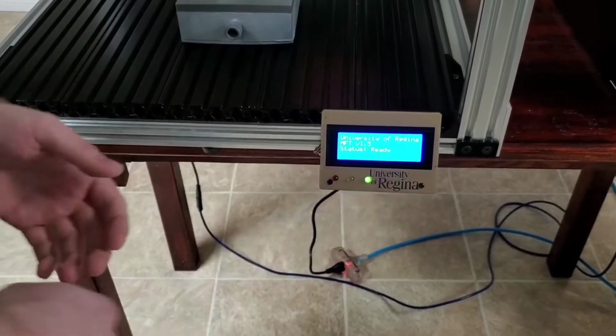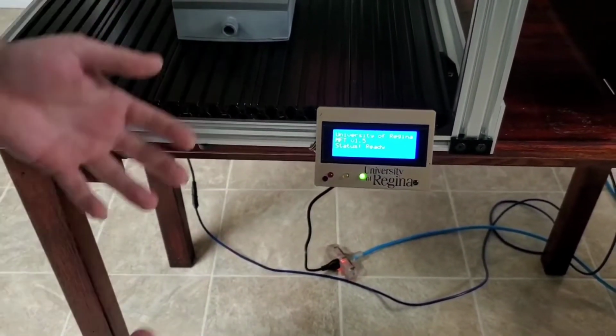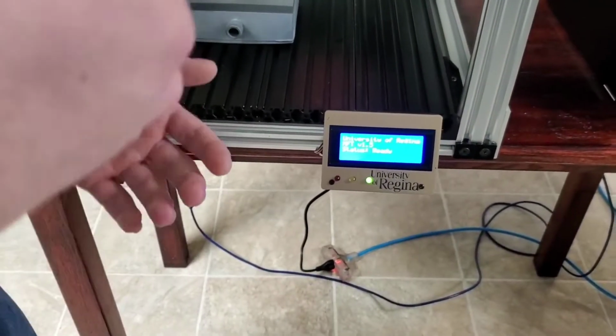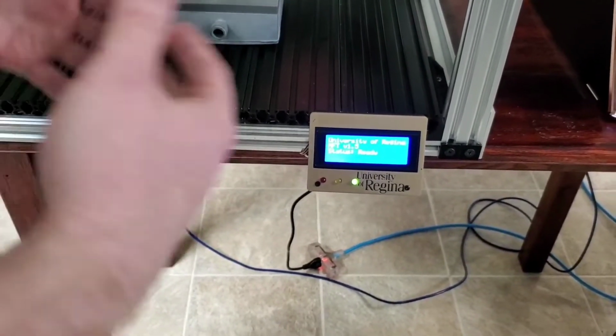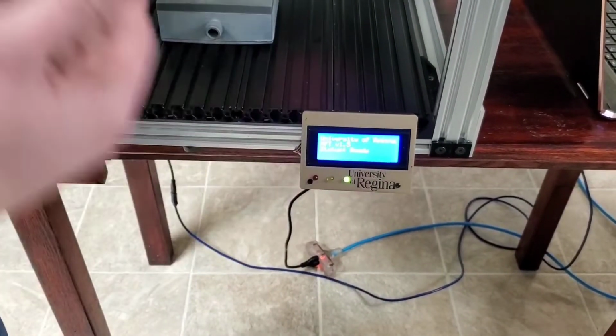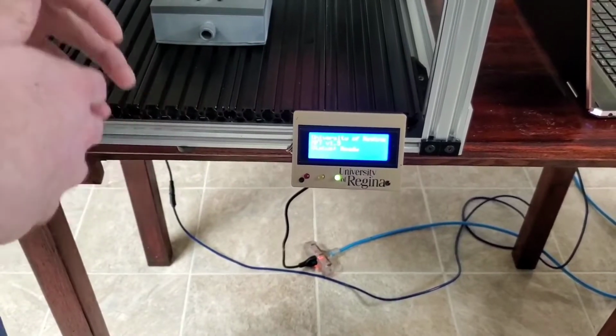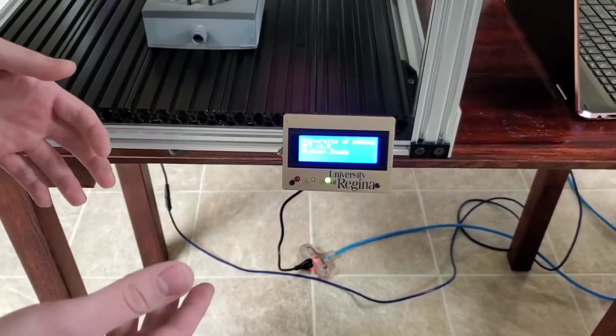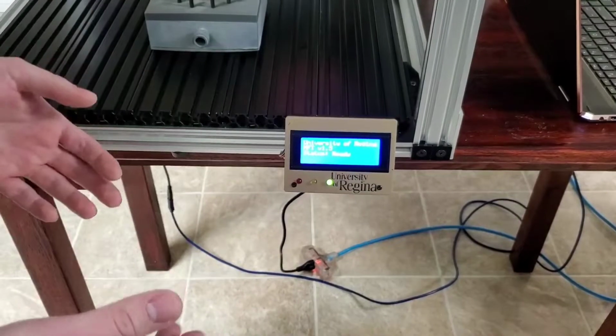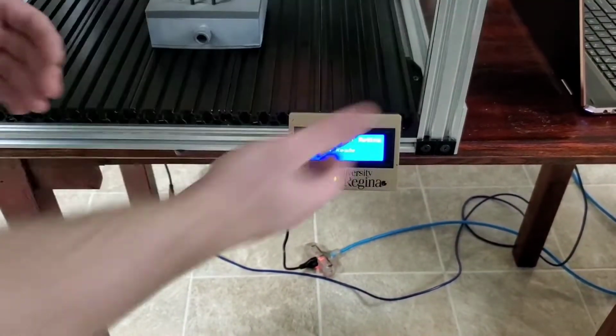The yellow LED is in the event we receive what we call a recoverable error. That might be receiving a single bad G-code error. And then finally, we have our fatal errors, our red errors. Those happen basically like hitting a limit switch. The machine stops dead in its tracks, no longer can go forward. It requires a manual reset with our stop button.